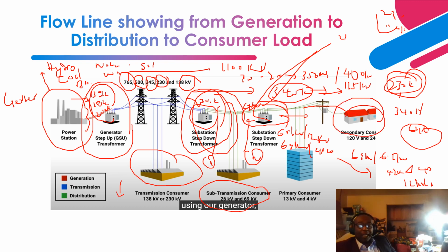So once it gets to the consumer on this pole, you have another transformer that steps the voltage from 480 volts to 120, or from 13.8 kV to 480 volts, before it gets to the consumer. So this is how the voltage gets to your house, the consumer end.